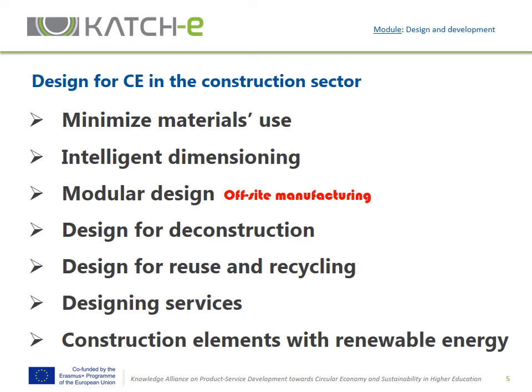Design for deconstruction. Designing construction elements in such a way that they can be taken apart is also an interesting approach, a LEGO approach. Design for high-quality future reuse and recycling. In the context of circular economy, this means not only in one cycle, but with a longer time frame in mind: second, third, etc. lives. This requires good quality recycling or upcycling.